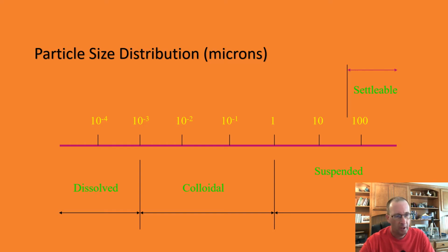As you can see here, the particle size of some of the solids that actually don't come out because of gravity gets to be super tiny. Anything that is settleable, or 100 microns or larger, is going to fall out because of gravity. Anything smaller than that is probably going to stay in the water column until you do something about it. That means either separating it physically by some special filter, or somehow spinning it out of the water column like they do with a swirl separator, or maybe even changing the composition of the water chemically like we would have to do with a colloidal solid.